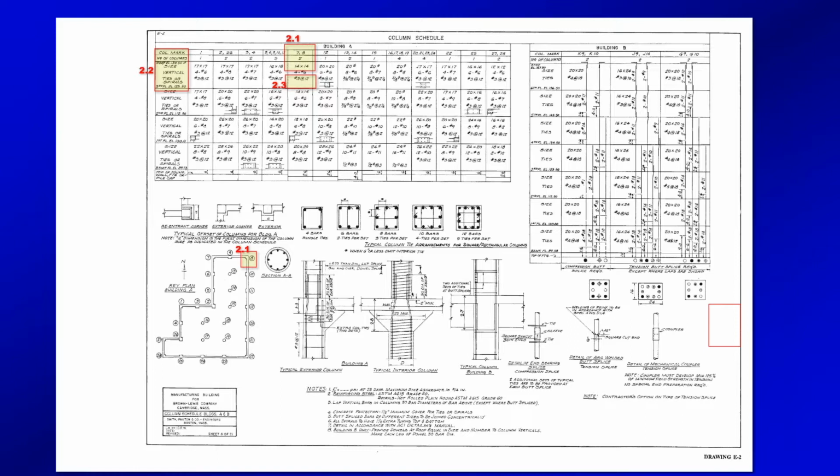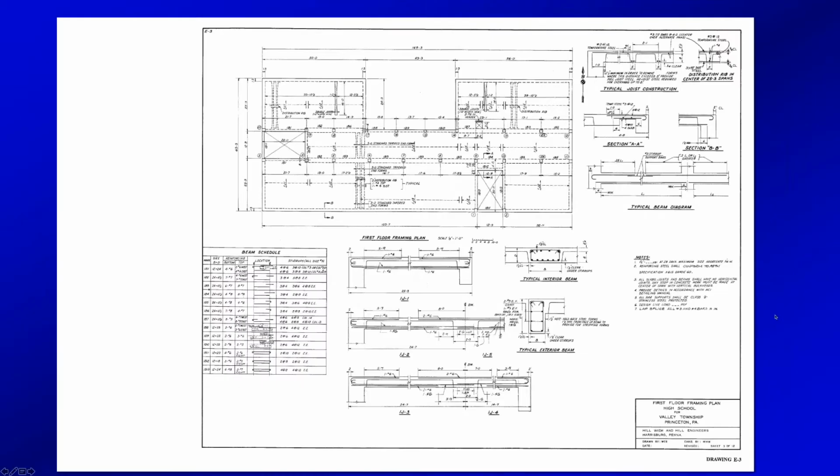That makes sense? Okay. So you can see here, there's a round column, and this little outside bar is considered the tie, and it's spiraling up the rebar cage. When you're over here in rectangular, you're looking at ties that just wrap around horizontally, like here, here, and here. Okay? Permission to go on. Good to go.